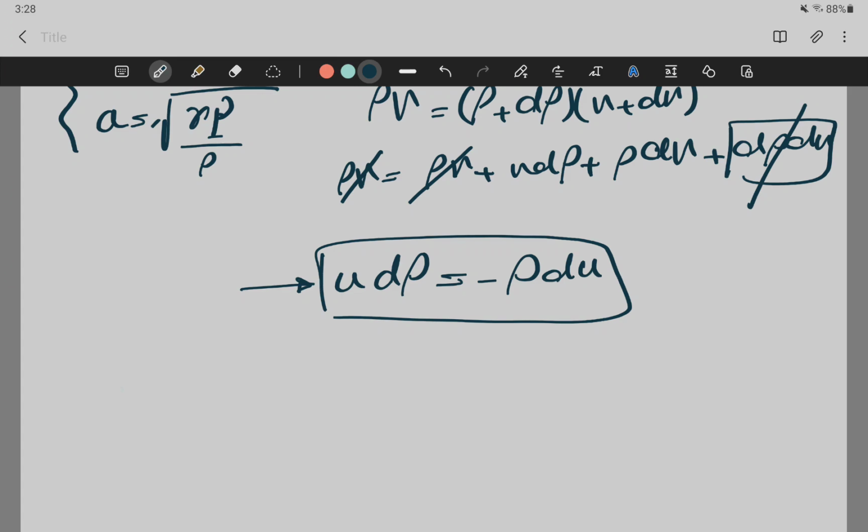So the force that is present here is actually only the pressure force, right? So for your F net, we are going to have the pressure force, which is going to be PA minus (P plus dP)A, right? The two forces acting in different directions. This is going to be equal to your m dot V in minus m dot V out, right? What is the m dot V in? That's m dot 1 V1, and m dot V out is m dot 2 V2.